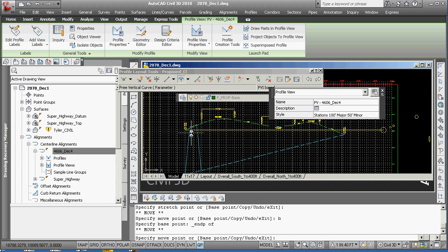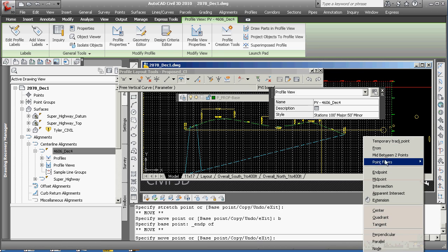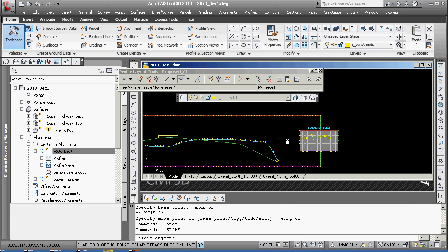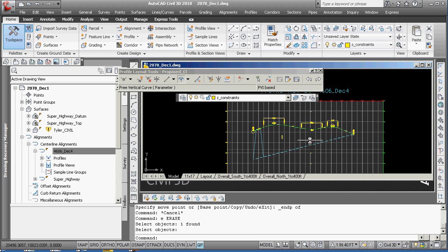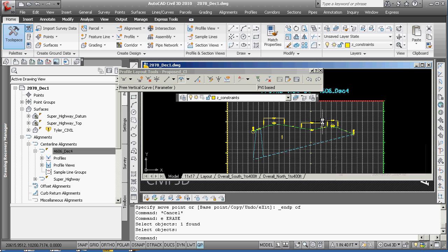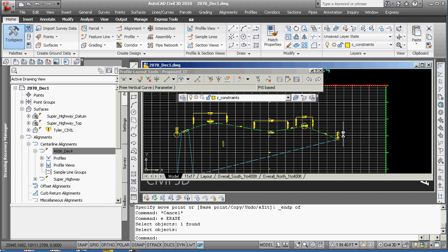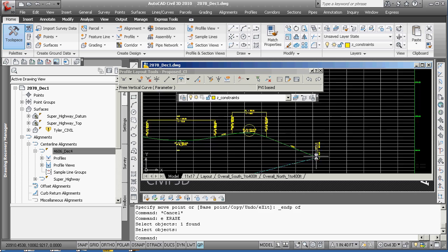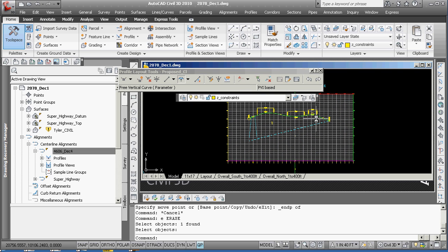Your second base point is going to be the end of that, and you should have everything back to where it was supposed to be. Why it acts like that, I don't know, and I'm going to try to discover today. All of a sudden, you always want to look at your coordinates and see that, yep, things are looking about right and everything's good. File save on a regular and recurrent basis.